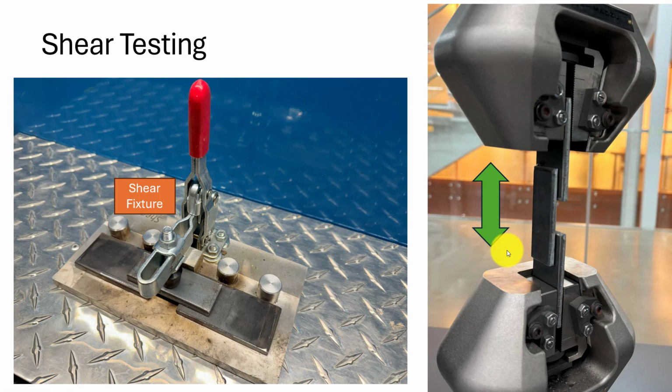So again, in this course, we're going to talk a little bit about three different testing methods. We're going to look at shear, bending, and torsion. Those are three simple equations we've learned in strengths and dealt with: force over area, Mc over I, Tc over J. You know those equations, and it's not that hard to apply them to weld design. So we're going to see some of that.